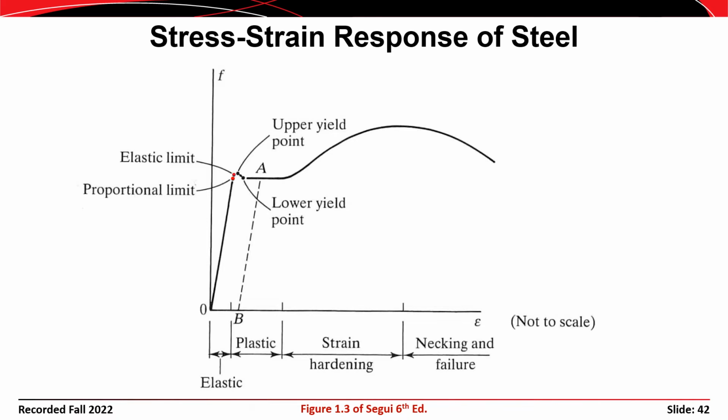This is the elastic limit. This is the upper yield point. This is the lower yield point. You don't see that in all cases. Typically, when you're testing steel, you try and test it at a high rate of speed. You could do more tests in the same amount of time. Plus, the material shows a higher yield point if you test it faster. And you don't always see all of these details, but it's important to understand the difference between the upper yield point and the lower yield point.